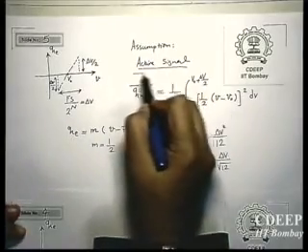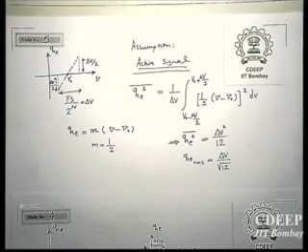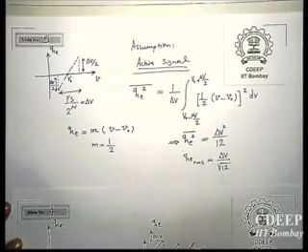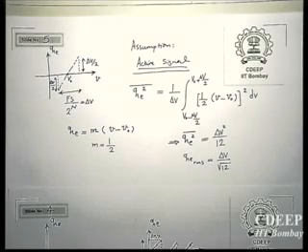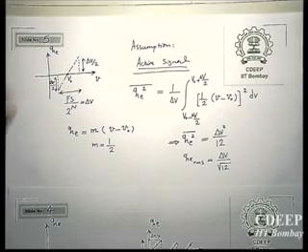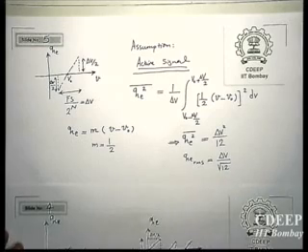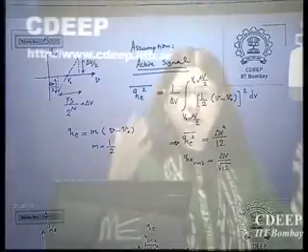So I stop it here, but at least now we have derived, by considering that the signal is very active, an idea of the average power in this noise, because the signal is very active, the signal itself is like noise, and the noise minus these reference values will itself be noise. Therefore now we have the RMS value of the noise. What is important now is only to have the RMS value of the signal, and then the ratio of them will give us an idea of the SNR for this quantization process, which is happening for any sort of data converter.